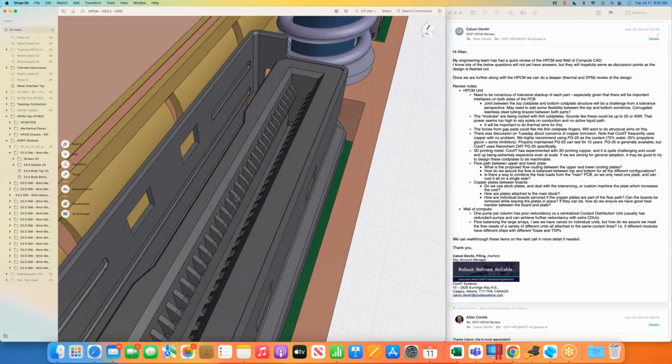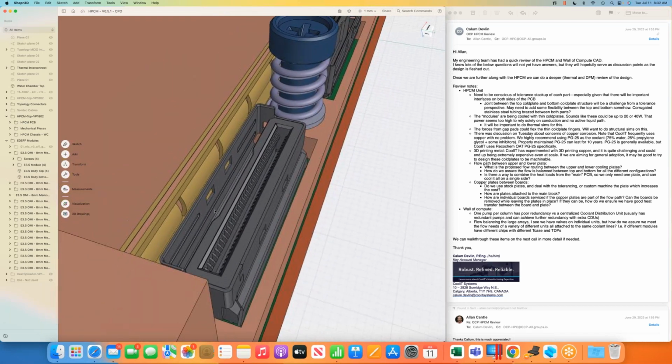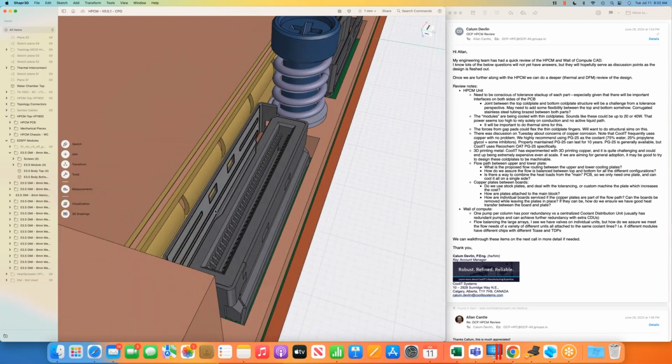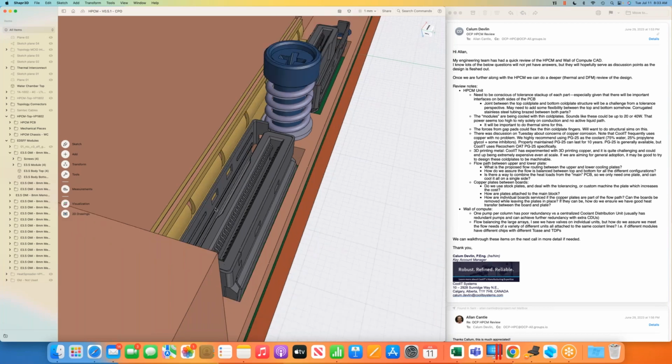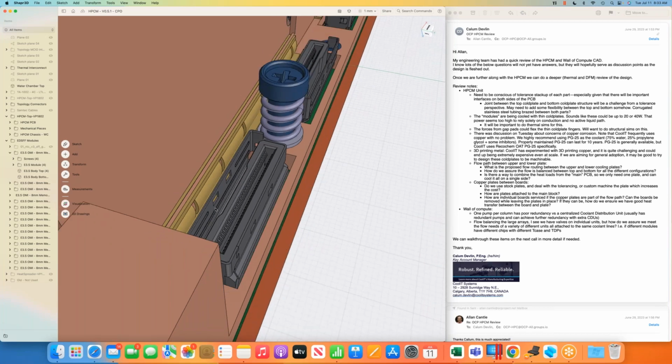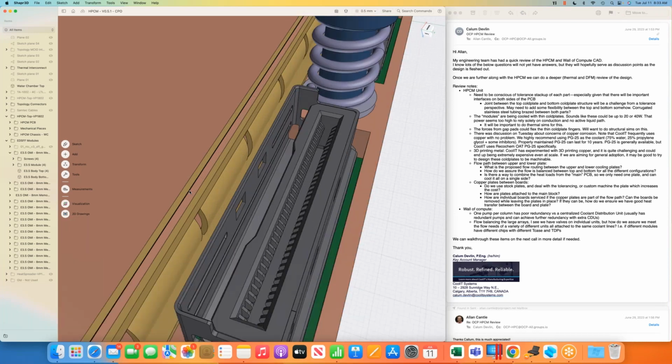Yeah, and so what you'd want to use to eat up the tolerance stack-up between these finger cold plates, I'm calling them, I guess, and the E3 peripheral media modules, you would want to use the thermal gap pad to eat that up. So that gap pad would be what's actually conducting the heat from the card to the cold plate. And so you have some compression on that gap pad, and you look at a tolerance analysis as well and see worst case, do you have?